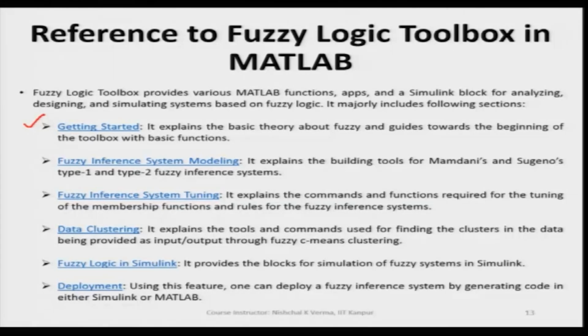And then the Fuzzy Logic Simulink is there, where we have a graphical user interface, and we can connect the blocks and implement the same thing using these. And then we have the deployment. So, using this feature given in MATLAB, one can deploy a fuzzy inference system by generating code in either Simulink or MATLAB.